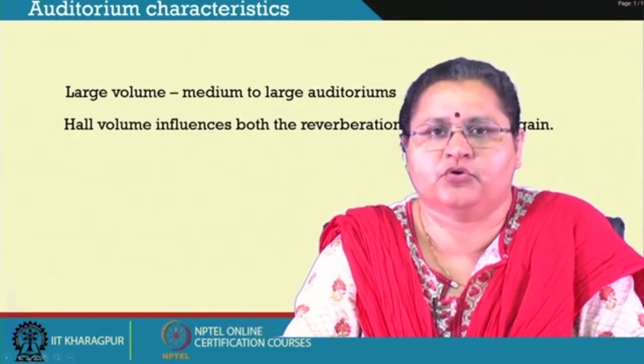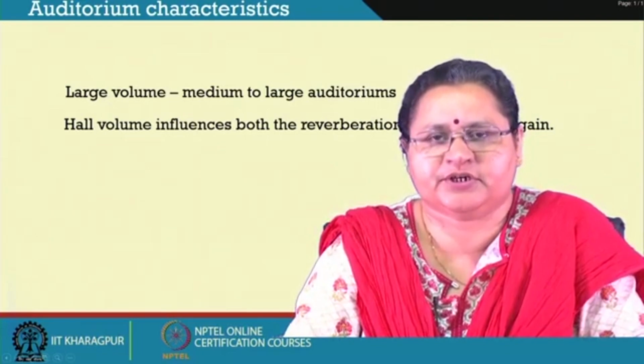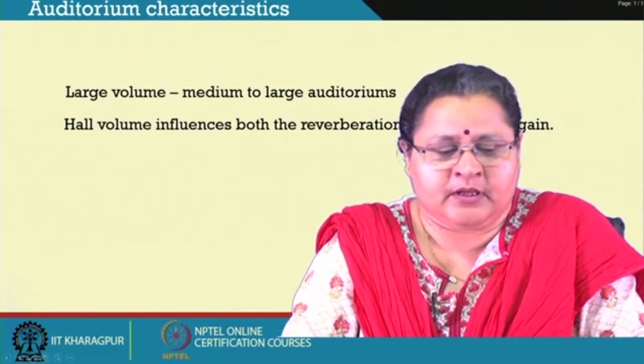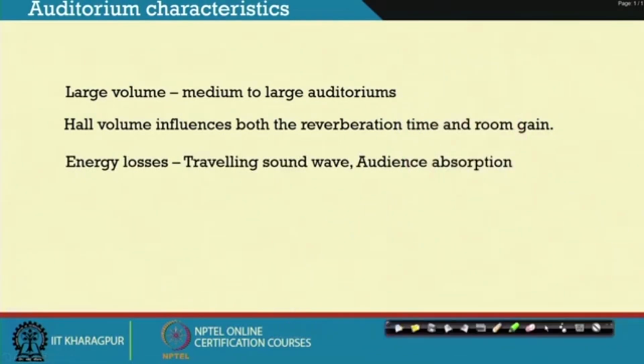So, we will also look into that later, but hall volume influences both the reverberation time as well as the room gain, and energy losses due to the travelling of the sound wave within the system are also to be accounted for. So, an auditorium is characterized by its large volume, its reverberation time, its room gain, and the losses of energy because of the travelling of the sound wave multiple times on multiple surfaces which are not very near, which are quite apart, are characteristics of an auditorium.